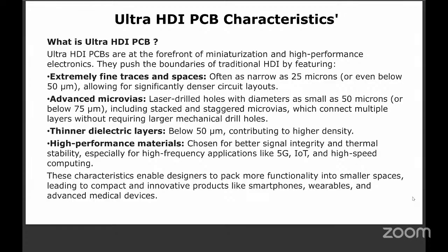Okay, let's define what are Ultra HDI PCB characteristics. What is the differentiator between Ultra HDI and say HDI PCBs? This may sound like a repeat for some of the persons who are following our channel. But anyway, those who are new, or even for a refresher, any trace width and gap less than 50 microns, even almost going towards 25 microns, is Ultra HDI.